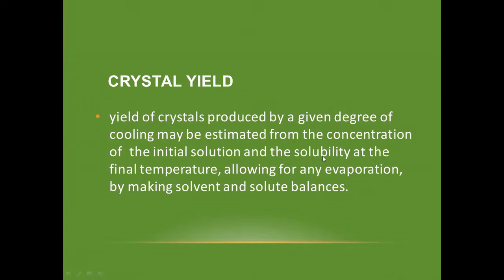So if the problem refers to the concentration of your solution inside the crystallizer, or gives the operating temperature or pressure of your crystallizer, this is the solubility of your crystals. That is also referring to the concentration of your solution inside that particular crystallizer. So final concentration C2 and your solubility are two similar things. This particular reference may be used by the problem.